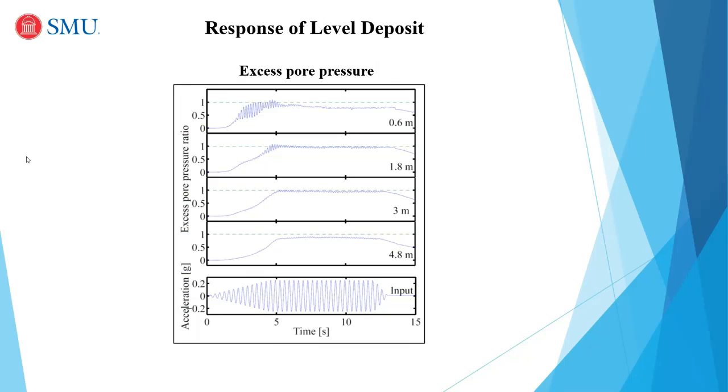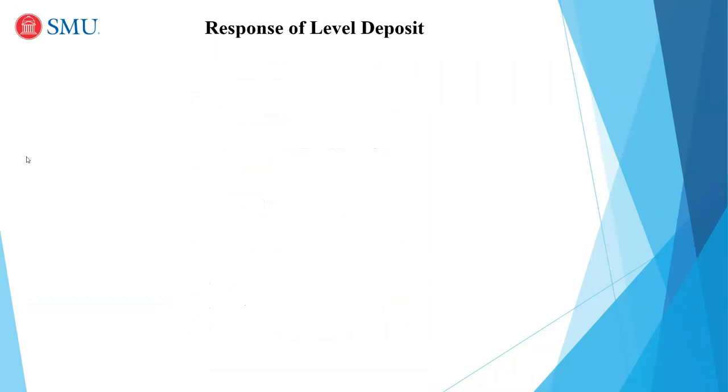and what we compute is the excess pore pressure ratio. That excess pore pressure ratio is the ratio between the excess pressure compared to the initial hydrostatic pressure, divided by the initial effective stress. If that excess pressure approaches the initial effective stress, again, that means your soil is essentially floating. That is represented here by this pore pressure ratio of 1. Once you see this line, this excess pore pressure ratio approaching 1, it means you have liquefaction and you have this instability phenomenon taking place. And that's what is happening almost over the entire deposit in this case.